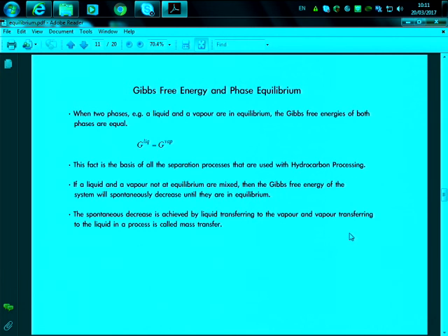This is very useful because it will tell you in a multi-phase flow basically what type of binary composition you have for a certain pressure and temperature. And if you have a change of pressure through the pipeline, it lets you know what the binary composition is at the end. Perhaps you had gas at the beginning, but then you change the temperature and pressure, and you end up with a multi-phase flow at the end. So you will be able to know that through this type of equilibrium concept. Okay?